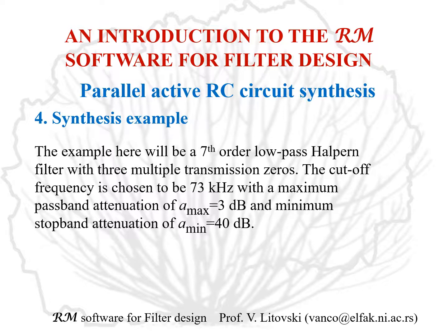As one could see, the synthesis of parallel active RC filters is a very simple process. The only step which is to be taken is calculating the residues, which is a simple one, and which is in general necessary for time domain analysis.